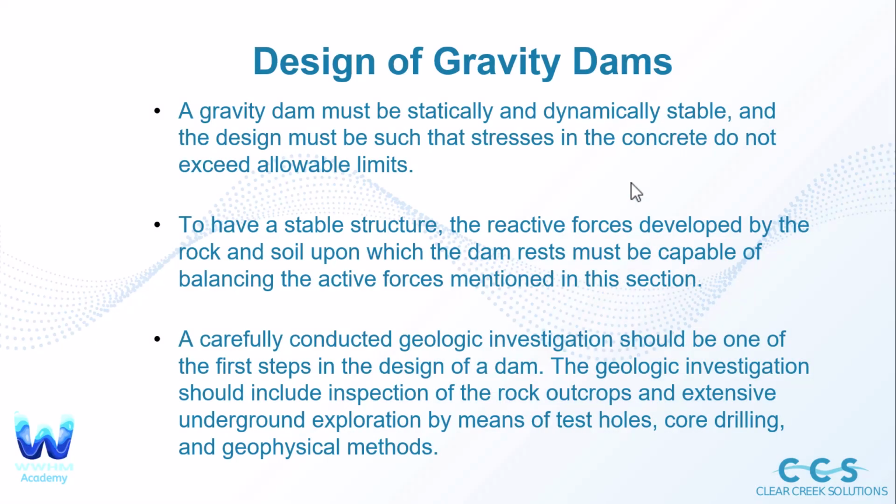But a gravity dam must be statically and dynamically stable, and the design must be such that stresses in the concrete do not exceed the allowable limits. To have a stable structure, the reactive forces developed by the rock and soil upon which the dam rests must be capable of balancing the active forces mentioned in this section.